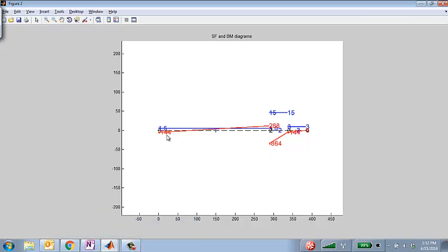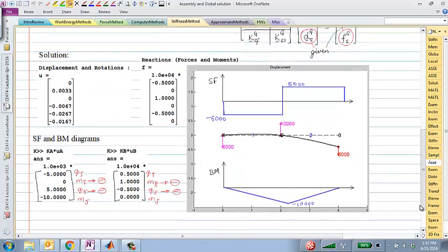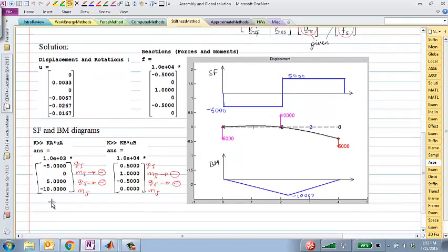And hopefully you all remember, for drawing the shear force diagram and the bending moment diagrams, we had to use the logic that we talked about last time: you go to each element, calculate k times u of that local element, you will get the q and m forces and moments for that element, and you need to take the negative sign of mi and qj, so that you can draw the correct shear force and bending moment diagram.